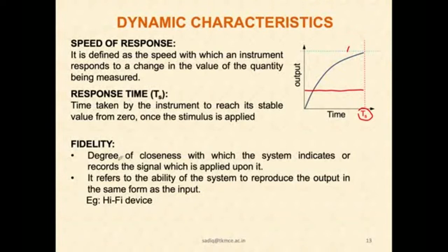Fidelity is another term. It is the degree of closeness with which the system indicates or records the signal which is applied on it. It also refers to the ability of a system to reproduce the output in the same form as the input. I will explain this. Take the case of a microphone, you are giving a sound, that is a signal. Are you sure that the microphone is picking the same signal as such, or is it losing something? If it is capable of recording the same output as such, it is a high fidelity instrument.